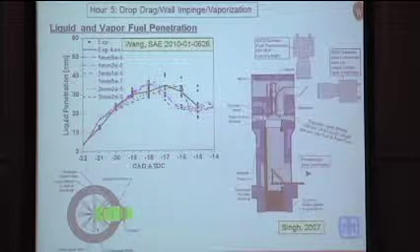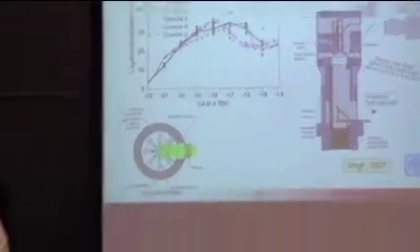What solution scheme is used for the particles? For which? Position of the particles? Yes. So remember I mentioned we're using the method of characteristics to solve the spray equation. So basically it's just a forward time integration. So the position of the particle, dx/dt equals v, the particle velocity. It's forward time integration.